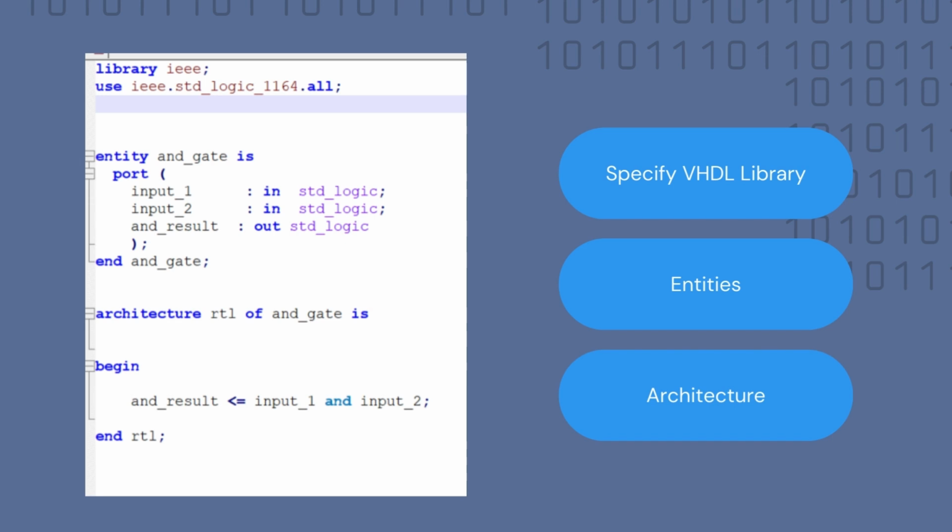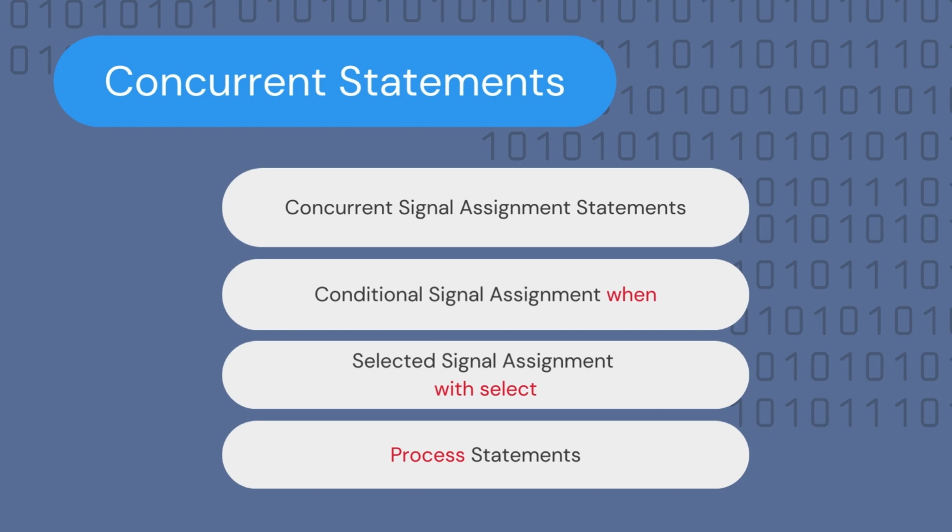As we've explored in our previous video, and as you may already know, the VHDL architecture describes how your VHDL system will behave. The architecture body contains 2 parts: the declaration section, right before the begin, and the body, or the begin to end section, where a collection of signal statements appear, and they are concurrent in their nature. We talked about concurrent statements in our previous videos and discovered the different types of concurrent statements and looked at 4 different types so far.